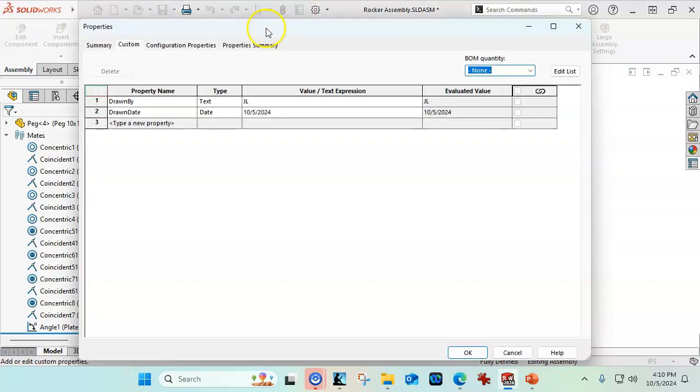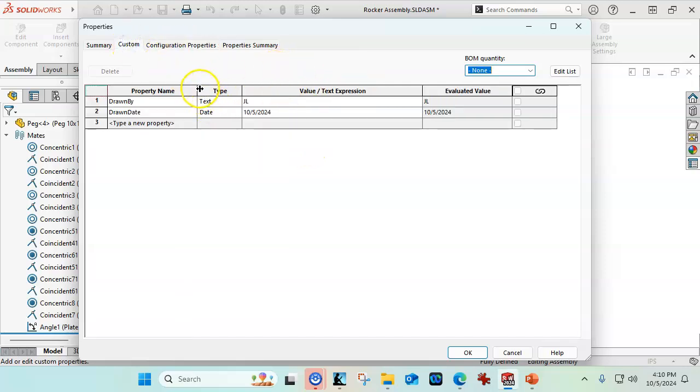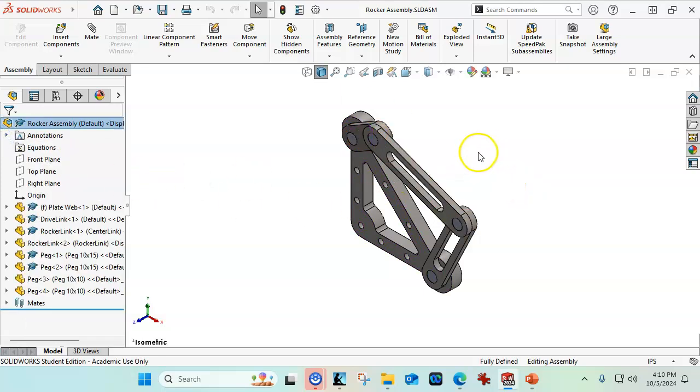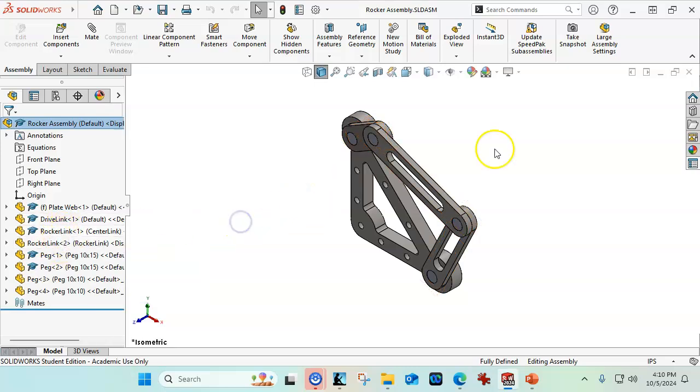And again, this is the optional part, if you are going to start tracking your metadata, building this out. Because this is not really going to drive on the configuration, you could put everything in the custom if you wanted to populate it. If not, we'll pick those up and deal with them later. All right, so I mentioned that the rocker link is the issue that I would probably just name link. We could have included the drive link and just had one part called link with those three components in it, and that would be fine. So, we have to make those decisions fairly early on.